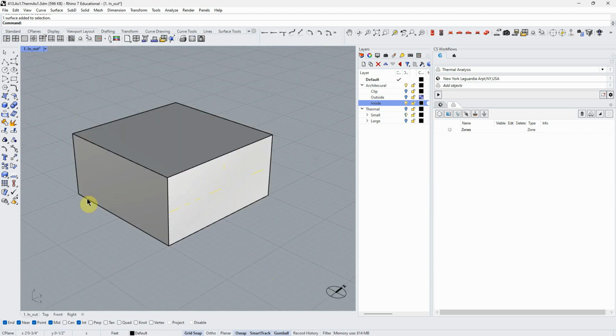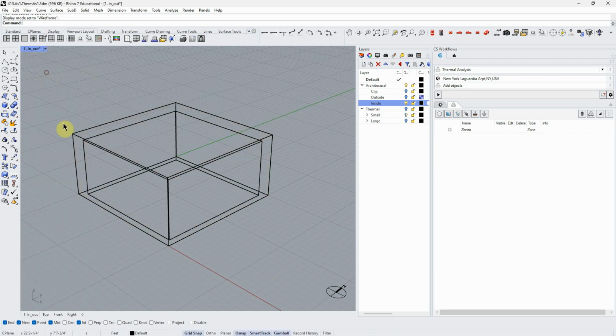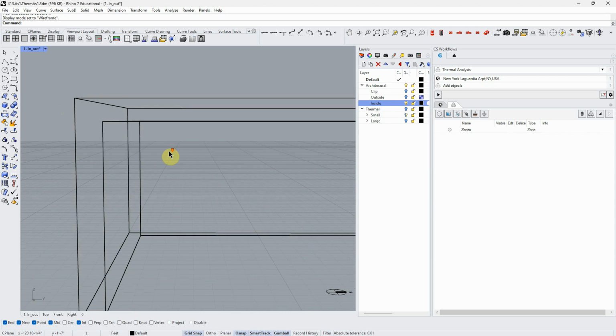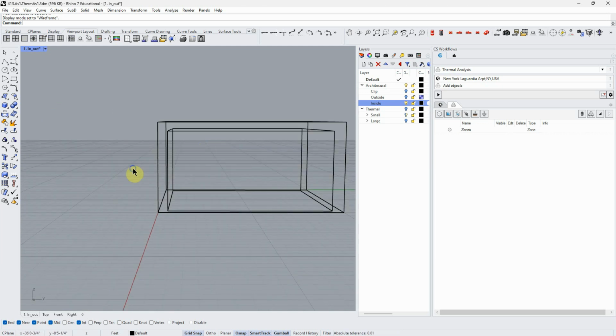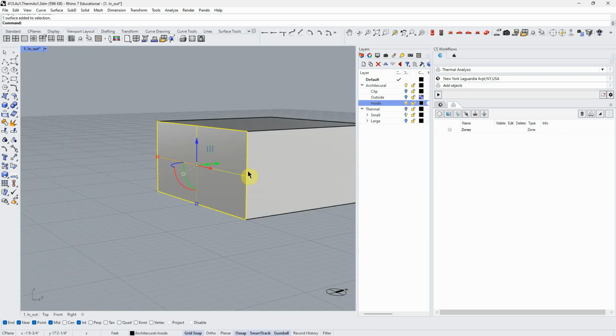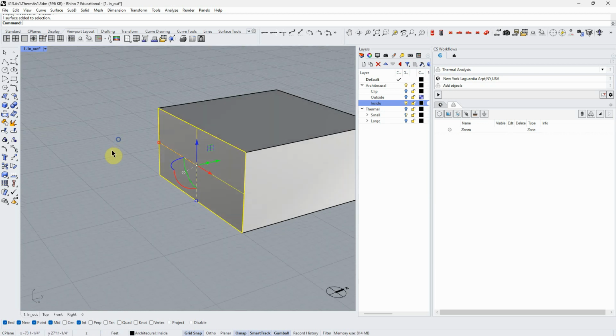And that's true because if, let's say this envelope here were 2 foot thick and made of concrete, or 6 inches thick and made of some kind of really insulative material, it would have very different characteristics from a heat flow standpoint, but the surface area that heat is moving through would be the same. It would be the exterior of the envelope.